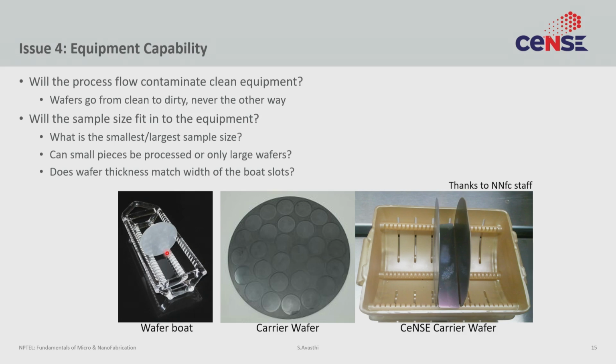Well, you can make a makeshift boat like this, but for that you have to create this piece of silicon and clean it during your cleaning step. So if you think of this problem in advance, you will clean all these accessories and create this mini boat that can hold a smaller sample. But if you don't think about the problem, you do all this cleaning, you go to the tool, you're ready to do your deposition, and suddenly you realize you can't. That wastes a lot of time, a lot of energy, and it's very demoralizing. So again, think ahead, think ahead, think ahead. Devil is in the details.